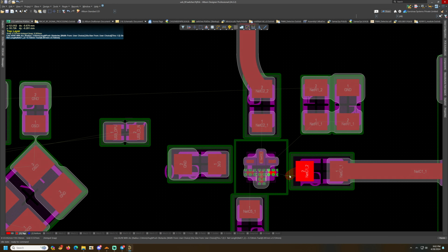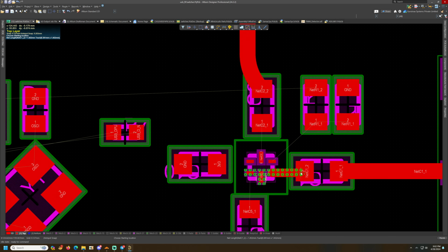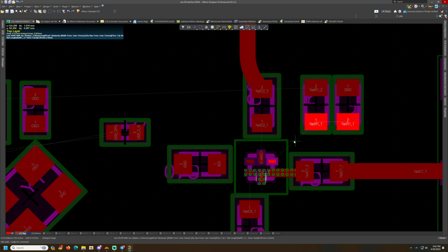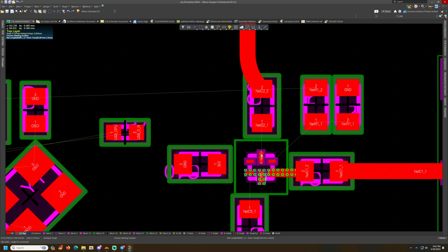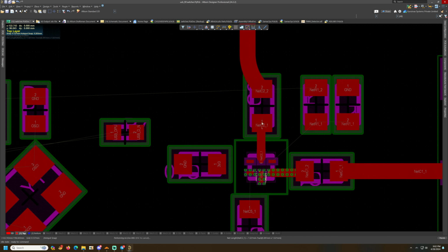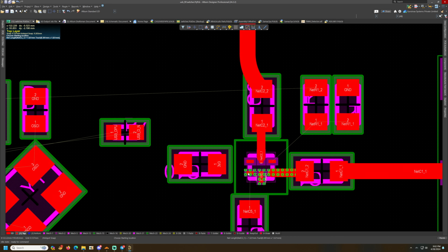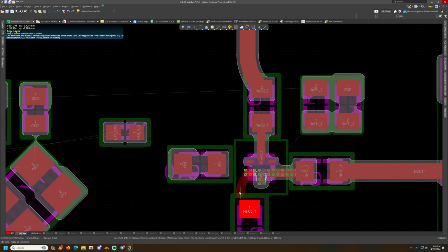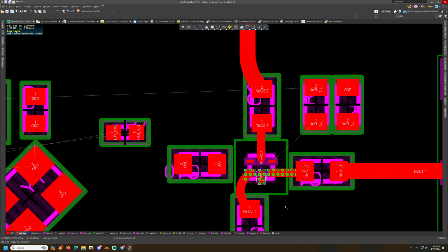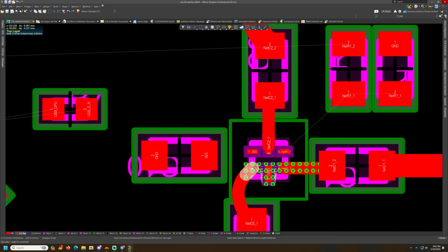Looking closely at the RF switch component placement, we can see the DC blocking capacitors are very close to the RF switch. I've made sure that the RF traces are as straight as possible, going from the switch pin to the DC blocking capacitor's pin, and then come the two decoupling capacitors on the right corner.